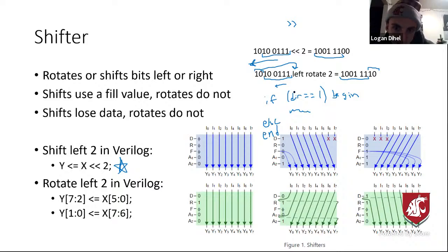The way I would do it is probably first: is it a shift or a rotate? Then is it direction up or direction down, like a 0 or 1? If it's a shift, you don't even have to pay attention to how many you're shifting by, because this operator will handle it. You could have said shift 4 and it will shift 4. So you're going to have about 3 layers of if statements, because you have to specify the direction, the number you're going to shift by, and whether it's shift or rotate. So we'll call that R.